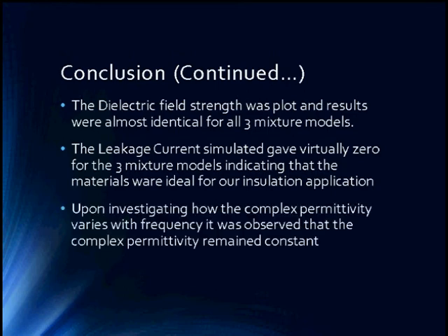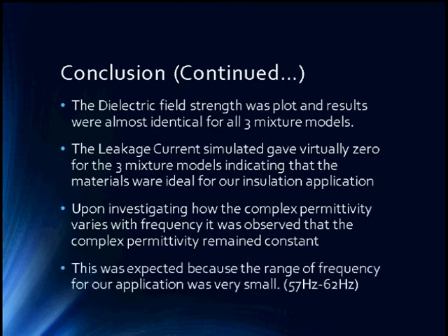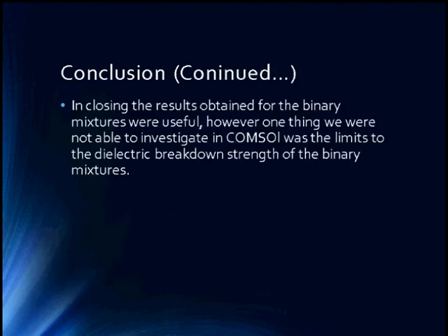Upon investigating how complex permittivity varies with frequency, it was observed that this remained constant, which was expected since the range of frequencies for our application, AC power, is between 57 to 62 Hz. In closing, the results obtained for the binary mixtures were useful. However, one thing we were not able to investigate in COMSOL was the limits to the dielectric breakdown strength of the binary mixtures.